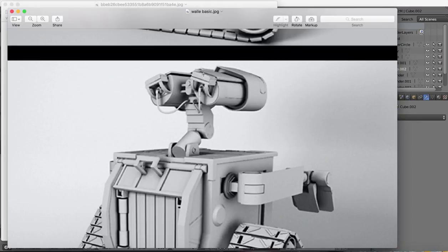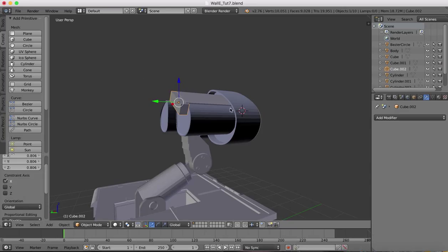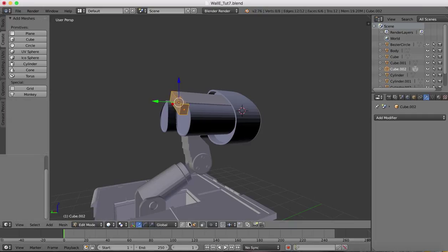Now with this, I'm going to curve those top edges. We'll also add in this detail here, and then we'll put the curved part underneath, which is supporting it. So first of all, back over into edit mode, edge select. I'm going to select this edge and this edge.